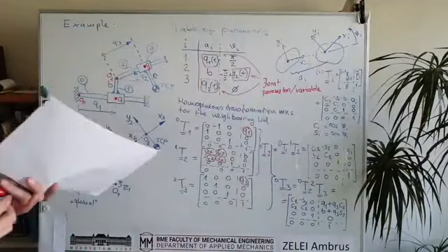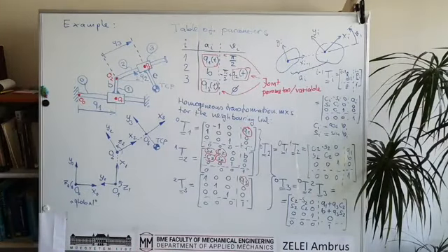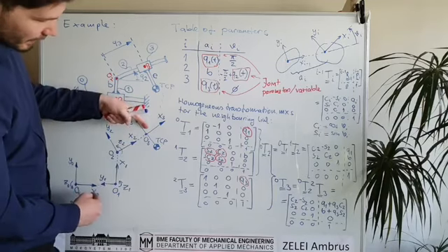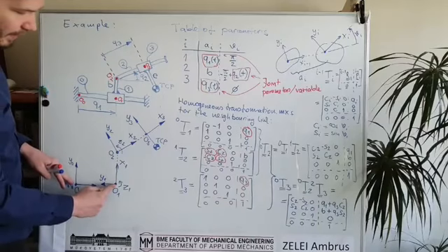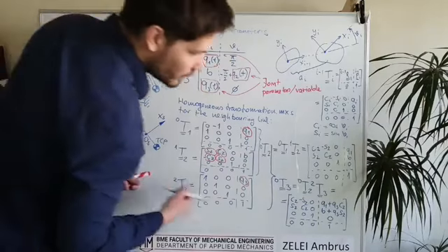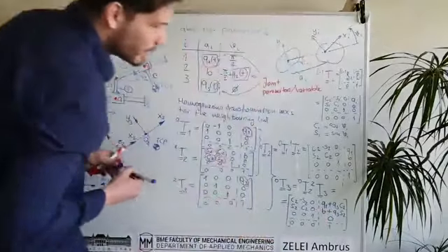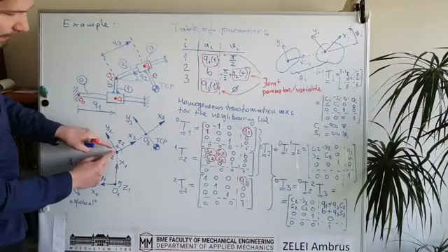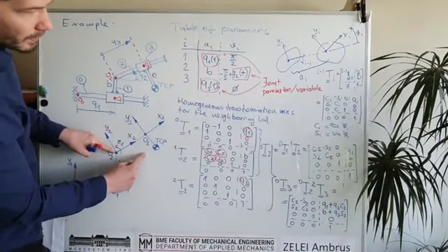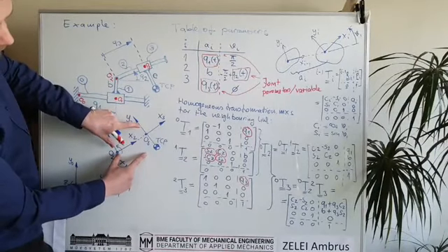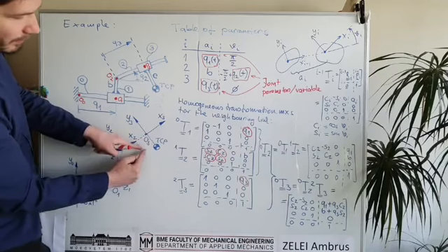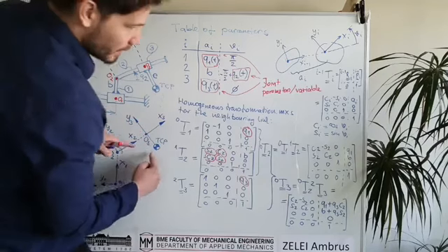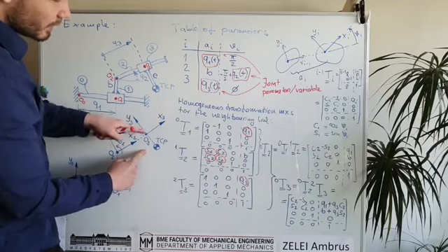And we can check this result by just looking at the figure. So the position of origin 3 is really given by this vector. So this is q1, b, and then we have to travel q3 times cosine q2 in the horizontal direction, and then in the vertical direction we have to travel sine q2 times q3.